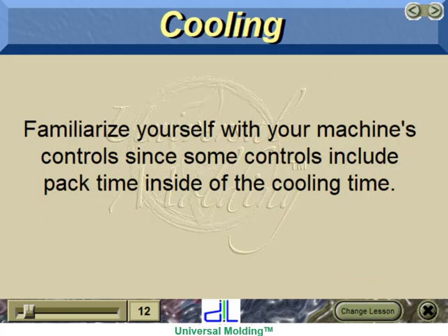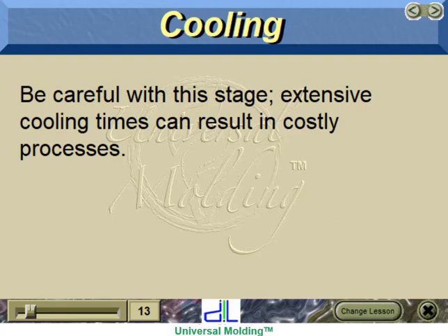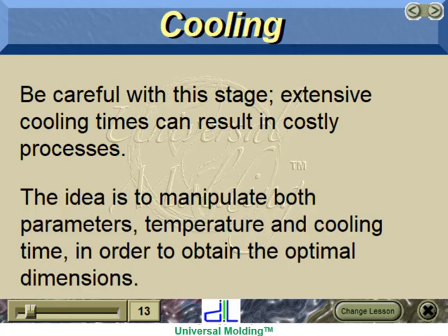Familiarize yourself with your machine's controls, since some controls include pack time inside of the cooling time. Be careful with this stage. Extensive cooling times can result in costly processes. The idea is to manipulate both parameters, temperature and cooling time, in order to obtain the optimal dimensions.